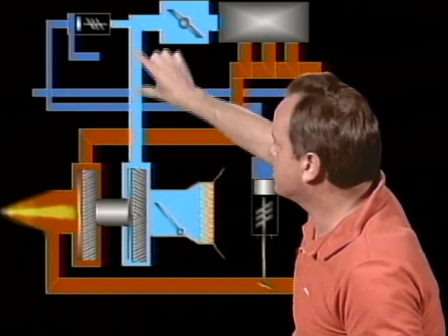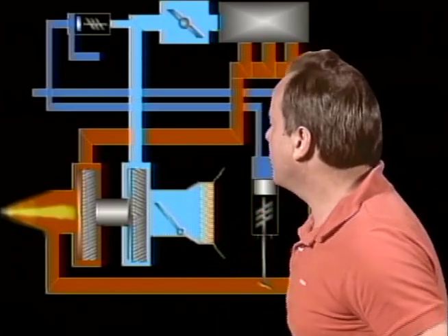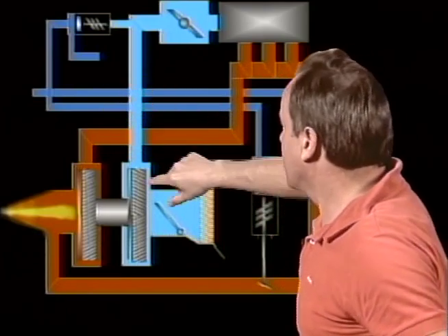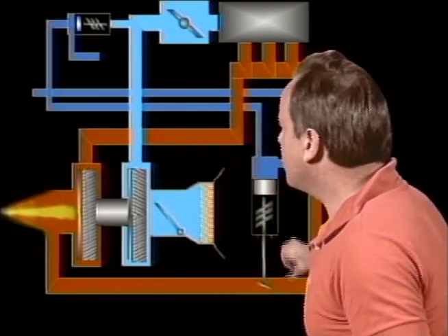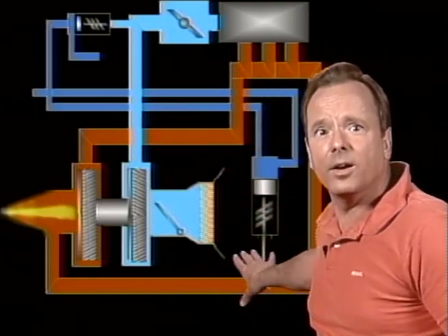Here's the upper deck pressure right in here. Ambient pressure is outside the aircraft, and it says we never want to compress this air any more than a 2 to 1 ratio, and so you have the pressure ratio controller, and once again it bleeds oil off of the wastegate actuator to open the wastegate, and that's the way it works. So they're going to ask you on the test, what is the purpose of a pressure ratio controller in a turbocharger system? And it's to control the position of the wastegate, and that's the wastegate right here, after the aircraft has reached its critical altitude.